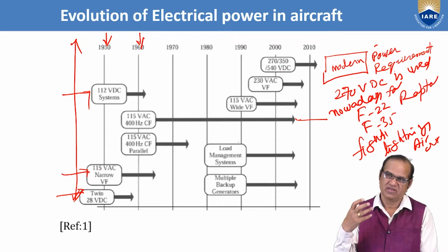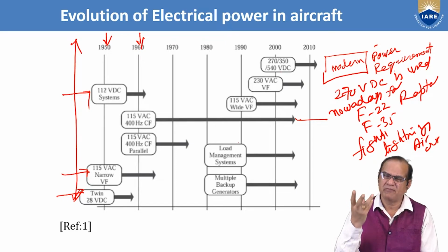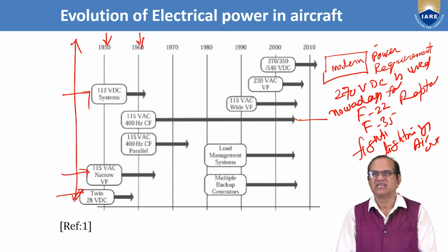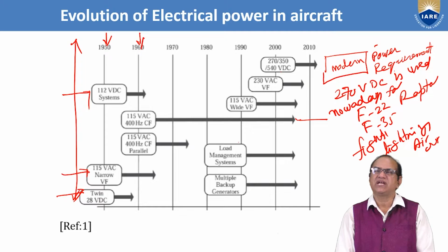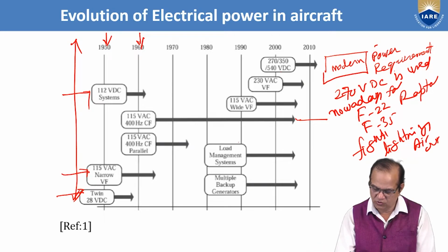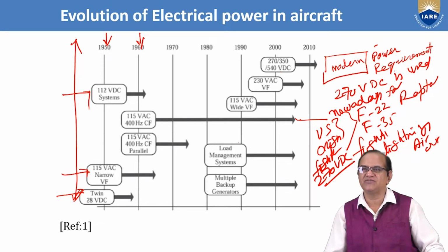The radar signature or the transmitting power, the radar will capture this, the electromagnetic waves which are generated from your AC current, and this is not good for a stealthy aircraft. So especially for fighter aircraft, US origin fighter aircraft, they use 270 volt DC, and these are a few advantages which we have given.